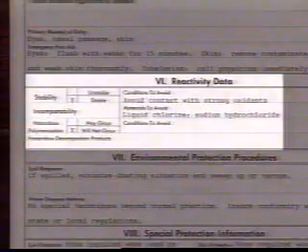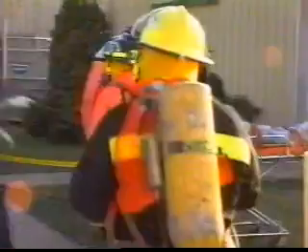The reactivity section lists any material or environmental conditions that could produce a dangerous reaction with the chemical, such as water, other chemicals, heat, or direct sunlight. First aid and emergency procedures are also listed. Take time to become familiar with the information in this section for any chemicals in your area. In addition, the MSDS provides information on how to handle a leak or accidental spill of the chemical. The final section of the MSDS lists any other precautions you may need to follow when handling the chemical.